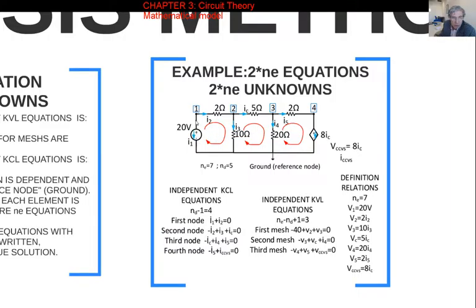But this current here for the independent voltage source cannot be chosen randomly, because the voltage reference for this element is given with the circuit. So we have to choose the current reference according to passive sign convention. That means the current reference starts from the plus sign and goes to the negative sign. Similarly, the voltage reference of this dependent voltage source is already given, so the current reference should be chosen according to passive sign convention. So that was in parentheses what was available and what we have added to this circuit.